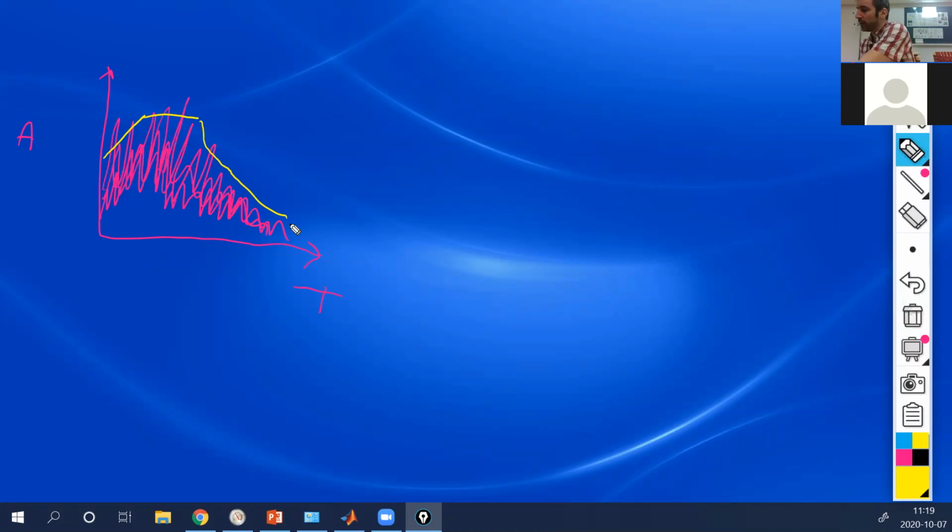So of course you can be very unlucky and be at the perfect frequency and have the perfect earthquake so that the response is larger than the spectrum, but that is supposed to be unlikely. So the yellow curve is designed to cover most of the earthquakes and for most of the frequencies.